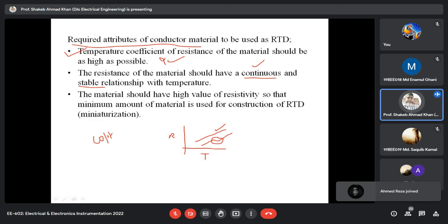So today that piece of copper has this characteristic. After some time it has this characteristic. So it is not stable, because there is a drift in the characteristic. Earlier, this much resistance indicated this much temperature. Now, after the drift, it is only this much temperature. So there is error, because you will measure only this one, since you know this characteristic.